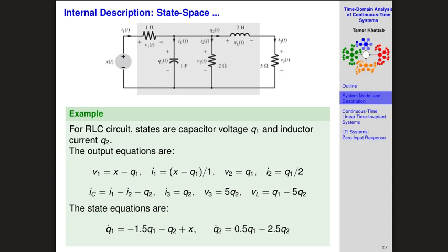So that's why only the two variables about the inductor and the capacitor, because they are the two time elements in that circuit, and why we pick the voltage for one and we pick the current for the other, because of the way they are related to each other. We want always the relation to be a differential equation rather than an integral equation. Even though an integral equation, you can always convert it at the end to a differential equation, okay? So this is kind of intuition. In reality, how you reduce the system and how you figure it out, there is a systematic way to do it, but it's outside the scope of this course, okay? Yes?